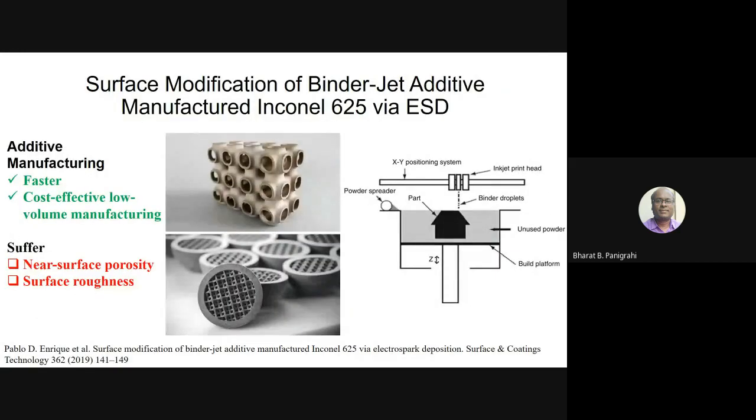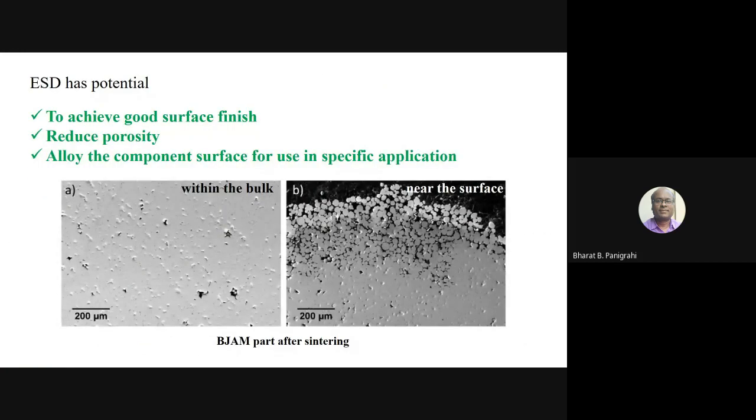I just want to touch on a very small section related to additive manufacturing. Additive manufacturing is available in various ways, direct deposition as well as powder. What you will notice here is that many times, if your parameters are not proper, or your powders are not proper, or the flow rate of your powder is not proper, there is a possibility of having surface imperfection. Those residual surface imperfections can actually be repaired using this method. You can see some other examples here.